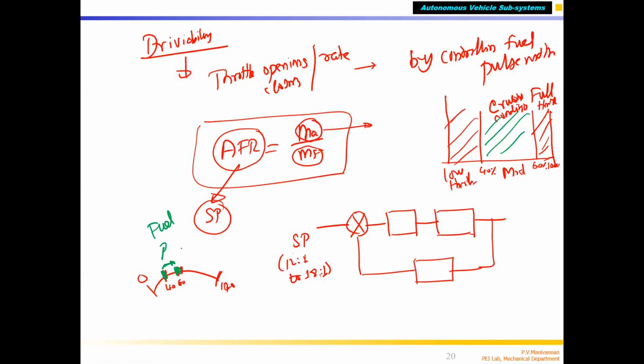At that time, the air-fuel ratio is generally maintained in a lean condition. Lean means maybe around 15 to 16 to 1. This is the air-fuel ratio where, as I already told you, you get maximum thermal efficiency, correct? All the fuel is burned, no fuel is wasted, because the air-fuel ratio is lean. That means you are not injecting too much fuel; you are putting in appropriate fuel so that all the fuel is burned and converted to hot gas, which pushes down the piston, converted to torque. So with more thermal efficiency you get maximum torque and less pollution, all those things.